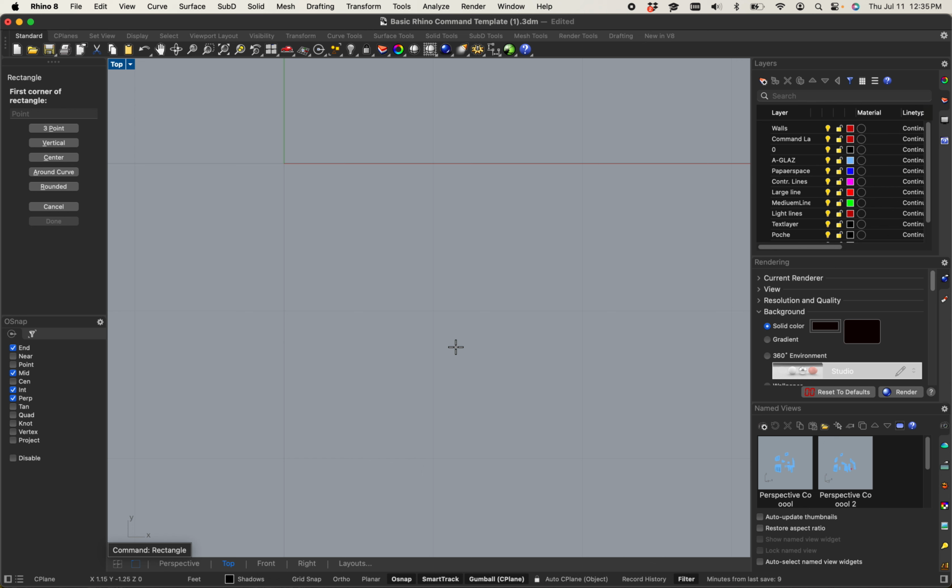If it actually is 1,000 miles, let's make it actually 1,000 miles. I wouldn't put it in a quarter inch scale because that would be ridiculous. What if my professor wants to see a picture of it at 1-to-1,000? Crap, I have to do all these calculations to make that bigger and true again. So anytime you're modeling, make it 1-to-1.